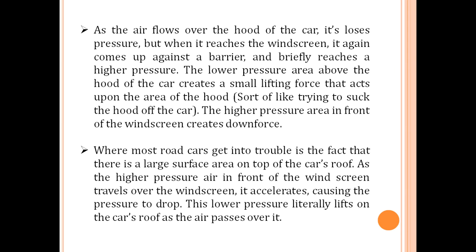The lower pressure area above the hood of the car creates a small lifting force that acts upon the area of the hood, sort of trying to suck the hood of the car upward. The higher pressure area in front of the windscreen creates a downforce. So as the air flows over the hood of the car or over the roof of the car, it loses pressure.